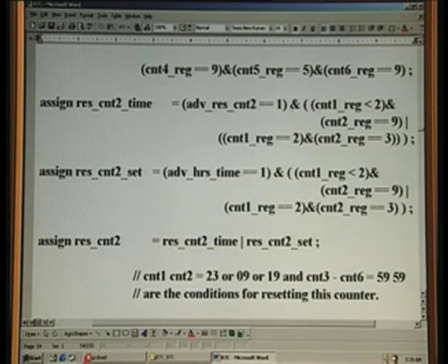And in each you also have two such conditions. For example, there is one more OR here for this condition, and that is the 09 or 19 condition or 23 condition, depending upon whether it is in advance hours mode, right. This is common anyway, advance reset counter here, and whether it is counter 1 2 or this, then also you need only to reset. So, this is common anyway. Note that the bracket starts here and ends here, right, and this or this expression, and then finally this. Okay. Is there any problem in the brackets? Hopefully not.